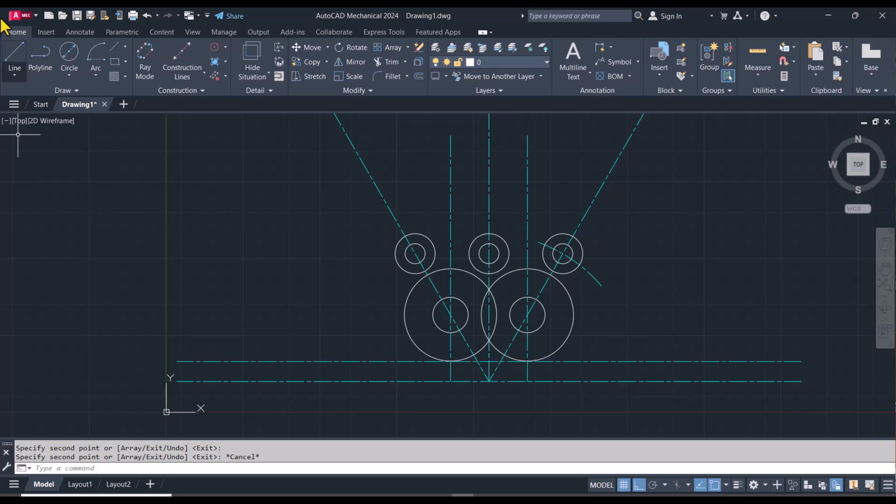And now I'll draw another center line, so I'll switch the layer to AM7 and then click on line. This center line is proceeding from this point here and makes an angle of 15 degrees to the vertical. So looking at where AutoCAD is measuring from, the angle that I'll need to put in will be 105. Okay, and then I'll hit enter.